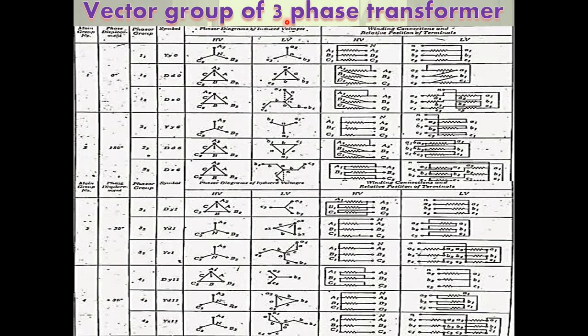Harmonic currents cause additional I²R loss, core loss, magnetic interference with protective relays, and interference in communication circuits. Harmonic voltage causes increased dielectric stress, interference with communication circuits, and resonance between the inductance of the transformer winding and the capacitance of the transmission line. Therefore, harmonics should be avoided.